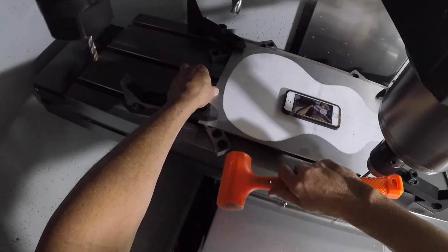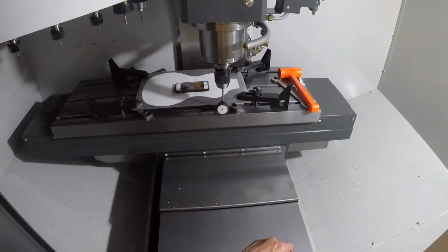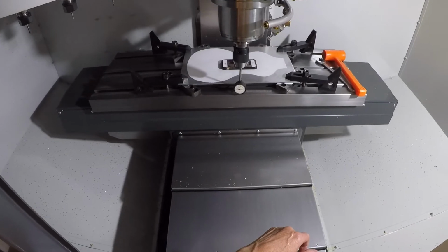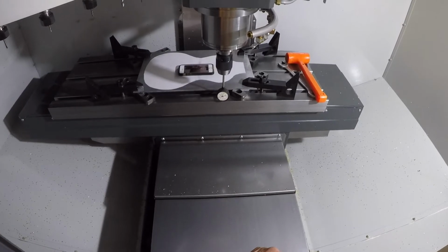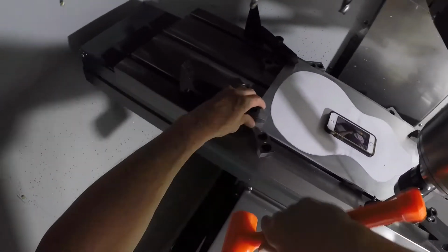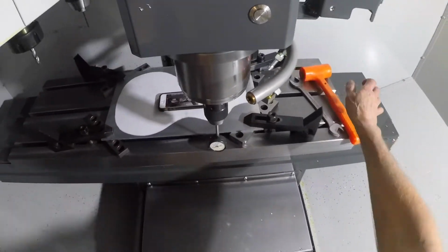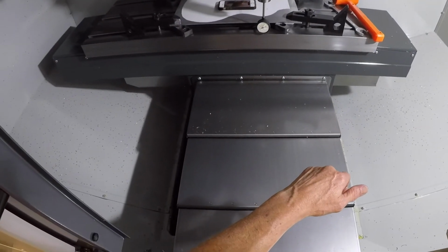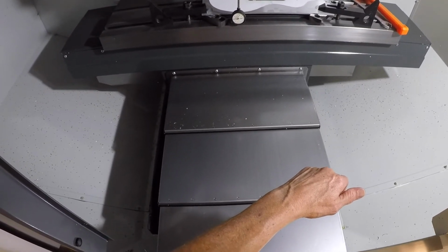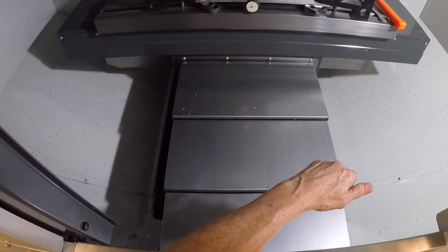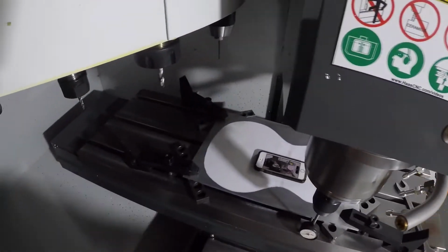I'm just gonna give this a little tap, might have been too much. And let's see what this says now. Same. All right, let me give this a little tap. I don't need to do this, but I just wanted to show you this is a setup procedure to get a plate in. All true. So now I'm at 40 and I'm at 35, so I'm 5 thousandths out.